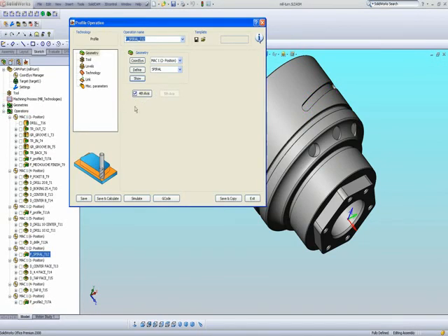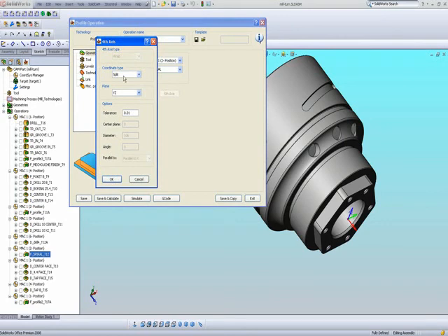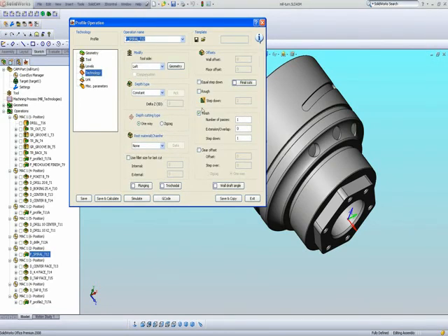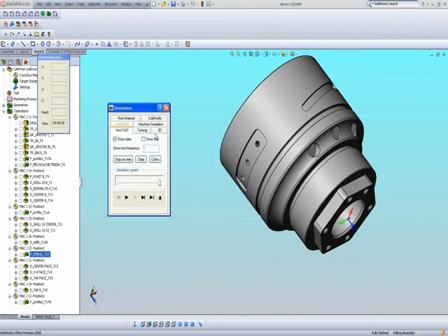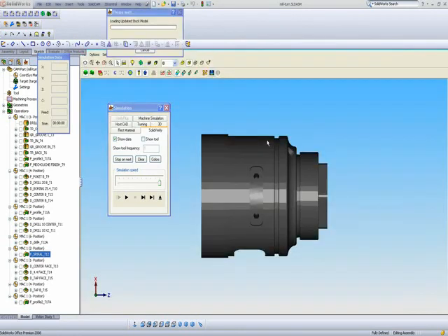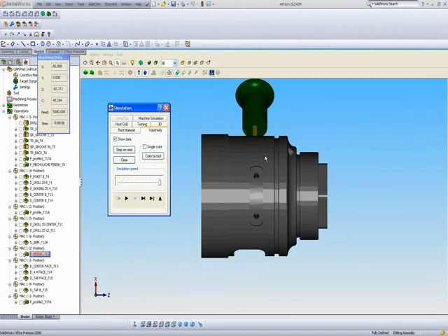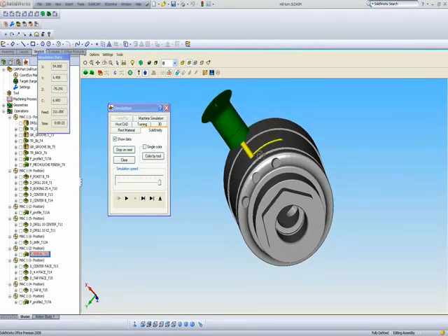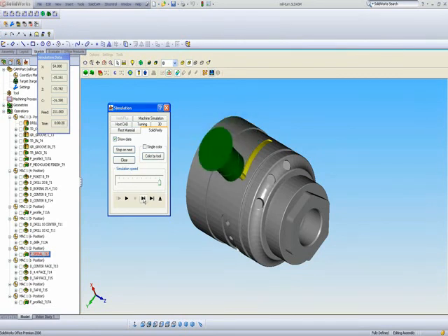And again, I'll be using the option of fourth axis, as I've done before. My levels, technology, simple, just as in any profile operation. And in my simulation, you'll simply note that the tool will go down, as seen here, go around, working on that angle, and then basically working its way back, doing that entire slot.